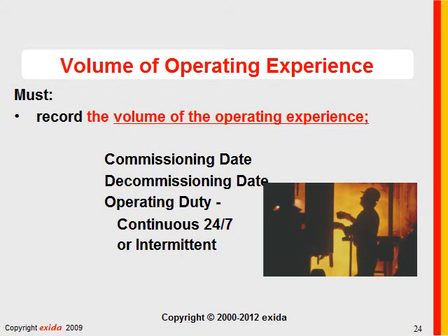Volume of operating experience. I immediately think of a bucket and filling it with water. And what's the volume in the bucket? No. We're talking about unit operating hours. How much time does this product operate? Now, we really should have the commissioning date, any decommissioning date, and the operating duty. I mean, is it a simple 24/7 where the instrument is basically on all the time? Or do you only turn it on 1 or 2 hours a day?